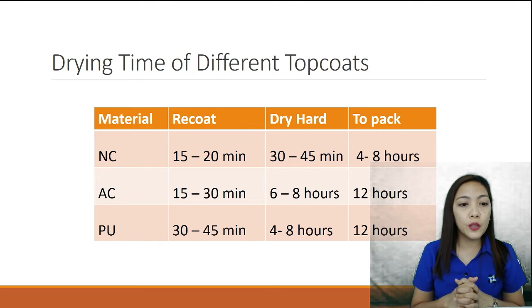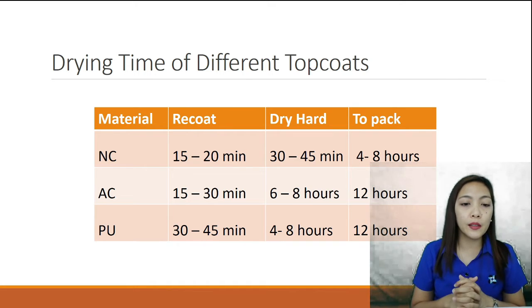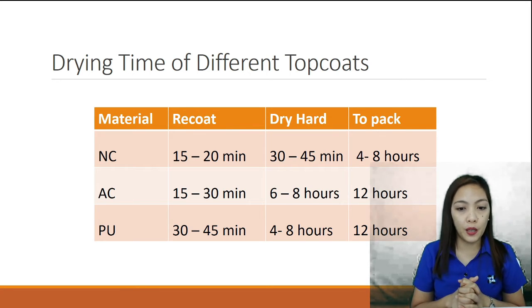So, as you will notice, it has the faster drying recoat time from 15 to 20 minutes, and a shorter dry hard drying time from 30 to 45 minutes.